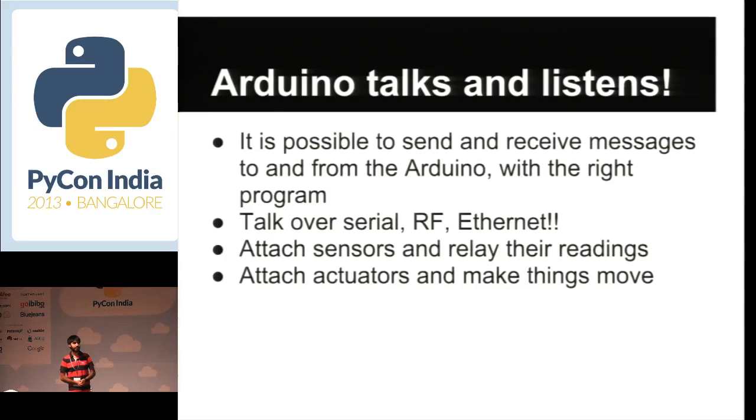But hold on, in the case of actuators, I do not suggest that you connect your actuators straight away to the Arduino board. The reason I say this is because your Arduino board is basically a microcontroller board and it supports a lot less current flowing through it. So if you want to interface a motor along with your Arduino board, you need to use something called an H-bridge or a motor driver. Because if you connect the motor directly to your Arduino, it's going to burn your Arduino because the motor draws a lot more current than your Arduino supports to sink or source.